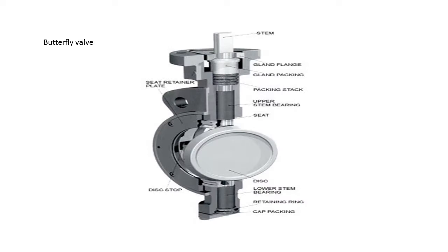The valve shown here is a butterfly type valve. This valve is also used to control flow of fluid through a pipe. The valve is made up of a body, seat, disc, stem, and an actuator or a handle. Operation is similar to that of the ball valve, which allows for a quick shutoff. The disc is positioned in the center of the pipe. Passing through the disc is a rod connected to an actuator or handle on the outside of the valve.